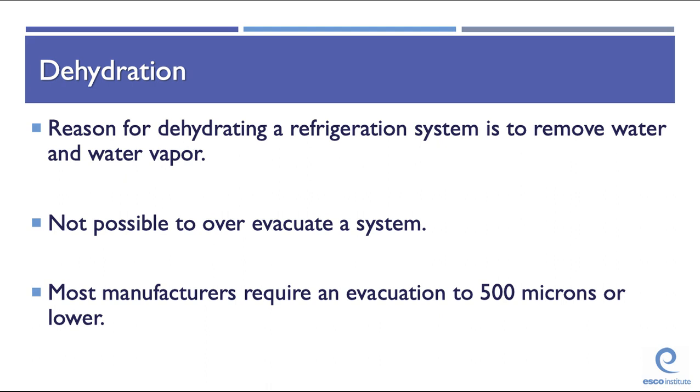Evacuation of a system is the suggested method for dehydration. It's not possible to over-evacuate systems. Most manufacturers require evacuation to 500 microns or lower.